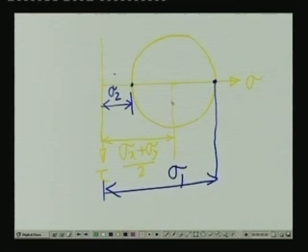And the third question: the plane where maximum shear stress acts, what is the value of the normal stress? Now, these are the planes where the maximum shear stress acts. This is the maximum positive shear, this is the maximum negative shear. The value of the maximum shear stress is that of the radius of the Mohr circle, tau max.